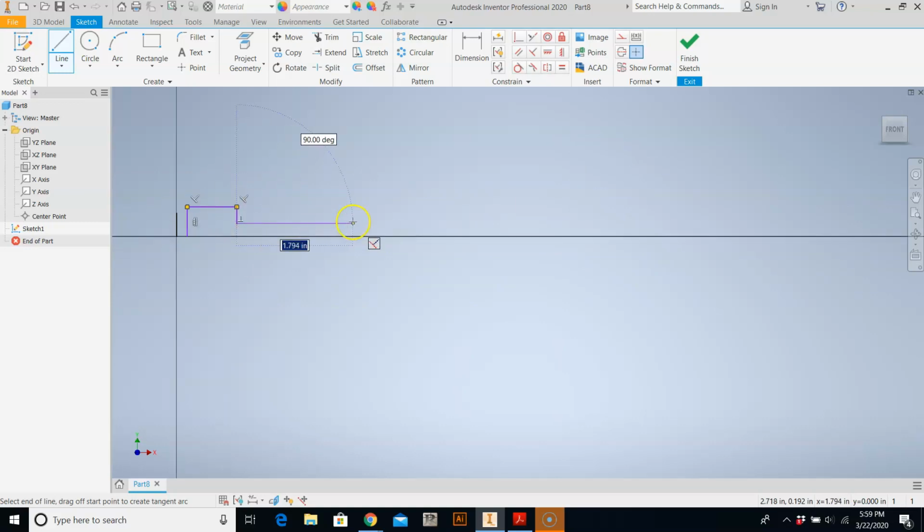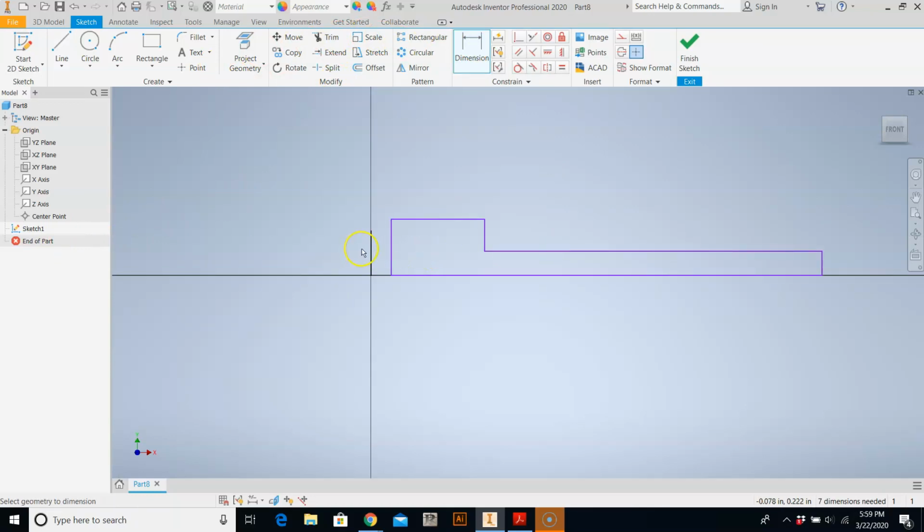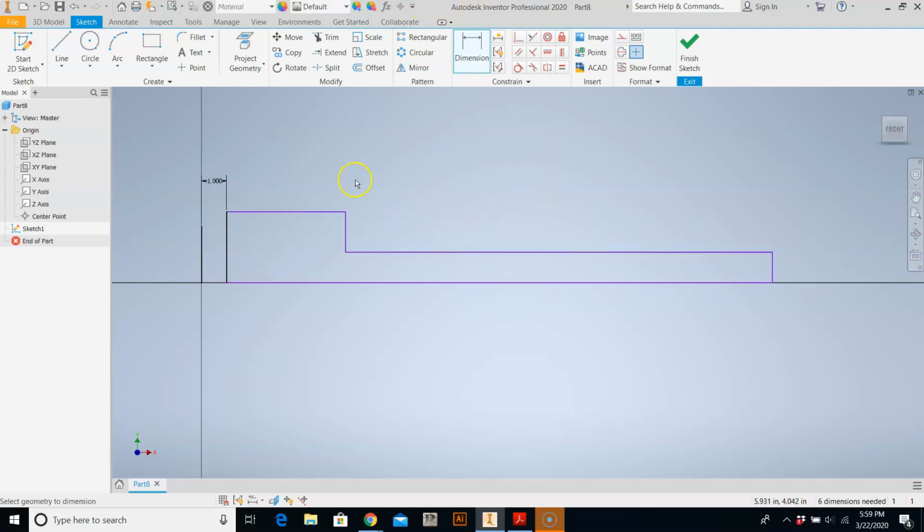And when I do the dimensions for this one, instead of using the radial dimension like we did on the sample problem, I'm just going to use a dimension that's actually the radius. So starting from the very beginning, here I'm going to dimension this inside hole. So this is the hole that's inside. That is a 2-inch diameter, so 2 divided by 2 is 1, so I can go ahead and set that as a 1-inch radius. Then I'm going to locate this next dimension here, which is 2.75.